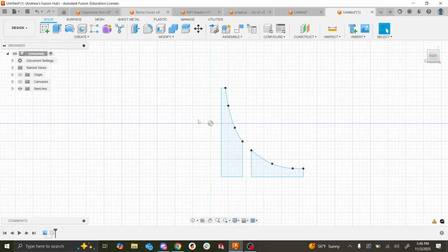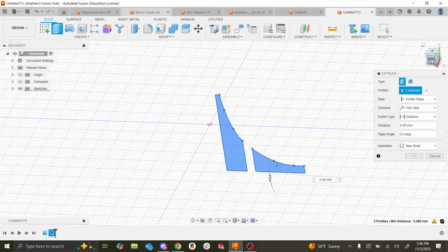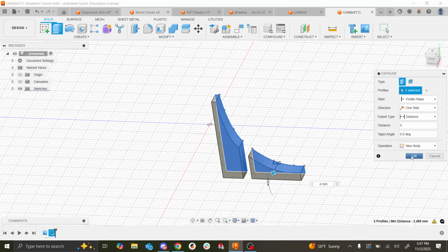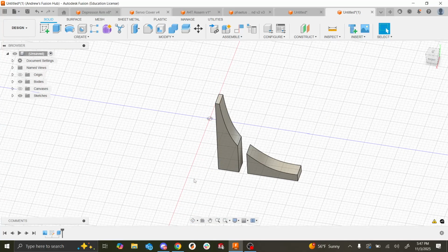I'm going to extrude this. Similar to last week, I'm purposely going to do something quote unquote incorrectly, so I can fix it later and you can see the difference it makes. So I'm going to start with a one-sided extrusion, but it would probably be better if you made a symmetric extrusion in this case. But I'm going to leave it one-sided for now, and then I'm going to adjust it later. So extrude by some amount. 4 looks good to me, and boom. So we have that engineering fountain, or at least a quarter of it. That looks good.